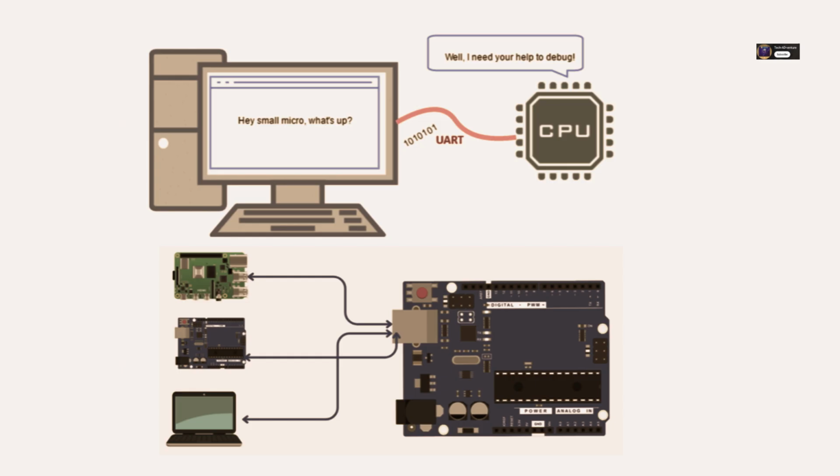A bootloader, what does that do? It's a small program that runs first, allowing you to update the main software on the chip just by sending the new code over the UART connection from your computer. Super handy. Its popularity really boils down to that simplicity. Just a few wires, easy to implement.